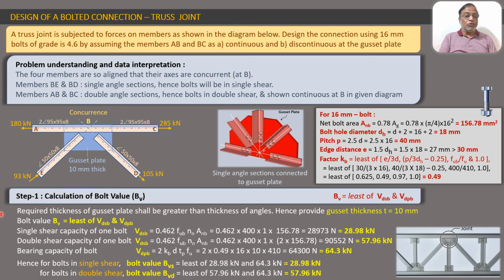Now we will proceed to step 1 of our solution. So step 1 is calculation of bolt value. By now we have already solved 2-3 problems on the design of bolted connection. In every problem, step 1 is the same. You have to calculate the bolt value, that is the value of the force that a single bolt will resist.